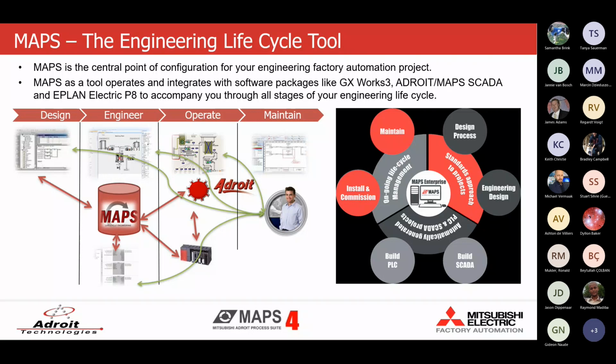As a quick example, someone makes a wiring change in the field on the PLC itself, rewires the input from input 1 to input 2, for example, and all you need to do is go to Maps and update the change in there, and Maps will obviously feed that through to ePlan, GX Works3, as well as your Maps SCADA package.